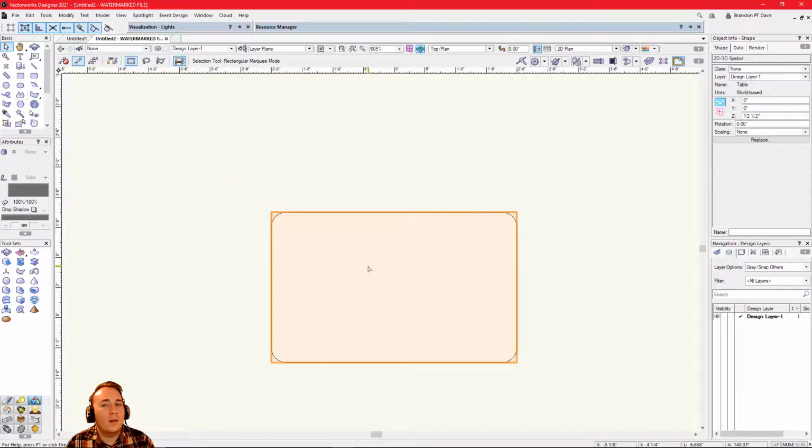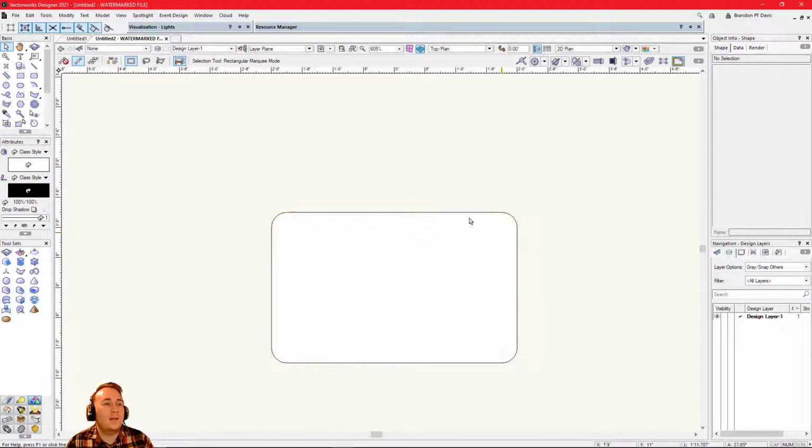Now, when it comes to allowing Vectorworks to generate the hybrid model, please note that more complex models can overwhelm your computer and cause it to crash. I recommend tracing the object yourself. This concludes the hybrid symbol tutorial. If you have any questions, let me know. Thank you.